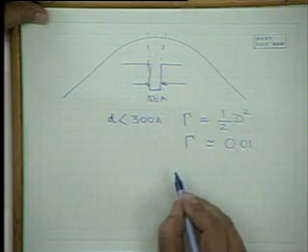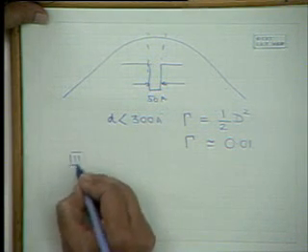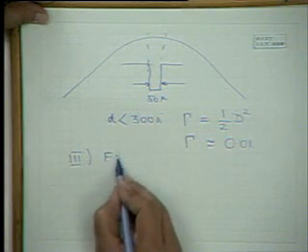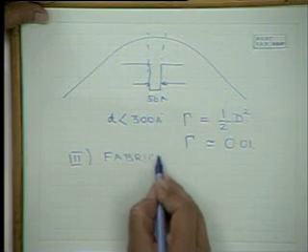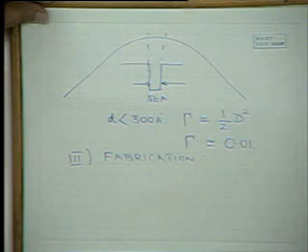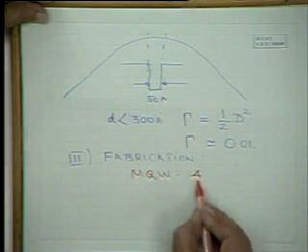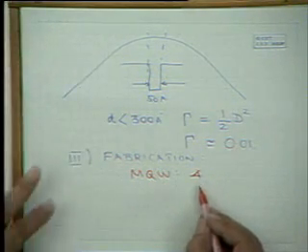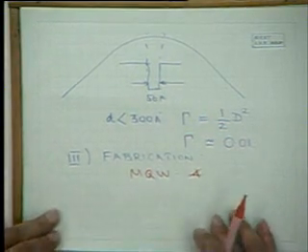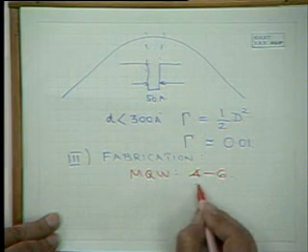So this is another disadvantage of single quantum wells. So you will go to more wells. But then the third reason comes: what are the fabrication problems? How many wells can you make exactly equal and with the same geometry? It turns out that most multi-quantum well devices have about, one can actually do this mathematically and calculate how the gain varies, how the differential gain varies, how J varies. The number of wells is typically of the order of 4 to 6.